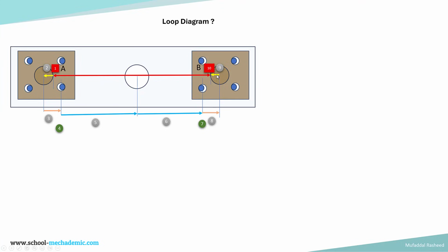And then we are going towards the left again. That is the diameter or radius of the post, variation in size of the post. And then specification number 10 is again the variation in the gap or the span because of the angle deviations. So there are 10 sources of variations, 10 types of deviations which can occur in this loop diagram, which we will see one by one, and we will list them down and calculate the maximum span. So first we will investigate 1 and 10, which is the deviation in the span because of the angle.